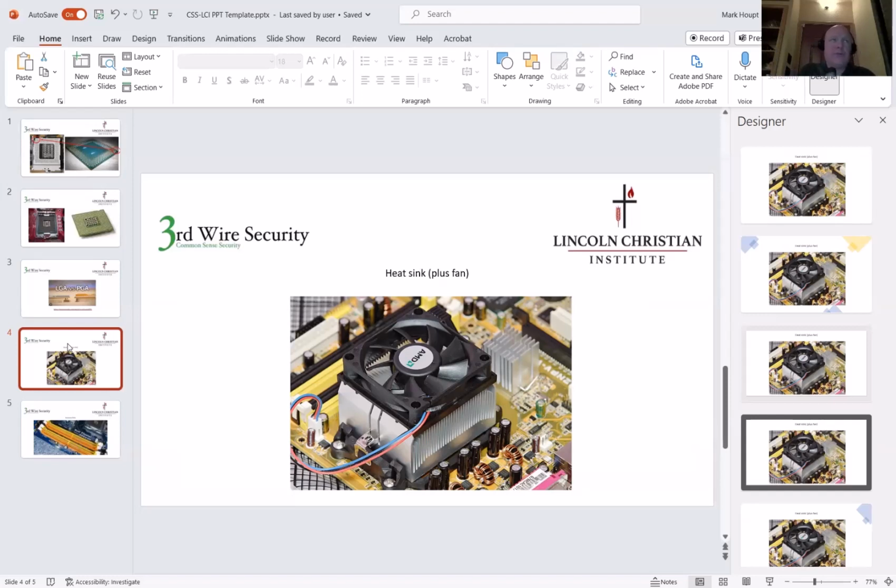It will remove the heat from the higher portions of those, because as the air moves from the fan across there, it will extract the heat, and as it extracts the heat, those higher in the posts will be cooler, and therefore the heat will continue to rise, not a true magnetic pull, but just the idea of moving upwards in that heat sink. And so it's a constant flow, like a river: a constant flow of the heat coming off of the CPU, moving upwards on the heat sink, the fan pulling that off and exhausting that out of the system.